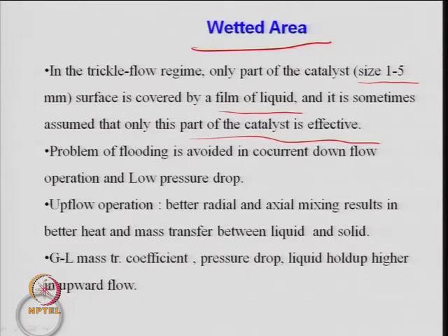The problem of flooding, again in the trickle bed reactor, you may have that kind of problem of flooding. But if you have a downflow operation, the flooding problem is minimized, but if you have upflow operation, the flooding will be there. So, that is again where the pressure drop issues will arise. When you have a downflow, then your pressure drop will be relatively low.